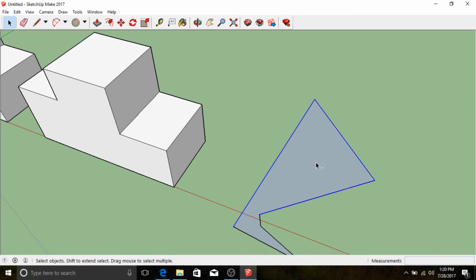You see this little plus minus that shows up, and that minus is up because if I select something by mistake or wanted to deselect it, I can just click on it once more. Okay, so if I wanted to delete these 3 edges, I can select them and then hit delete on my keyboard. I mean, I could use erase, but I like to select and then delete.